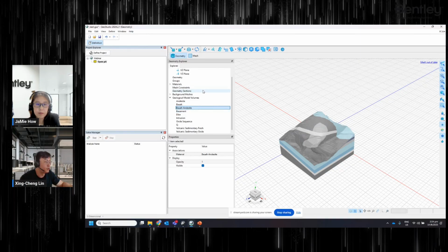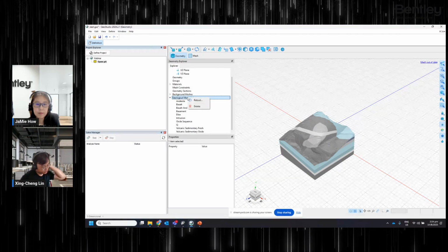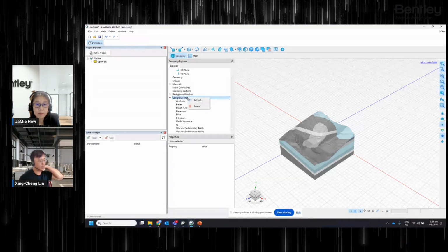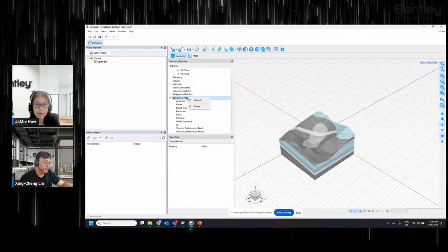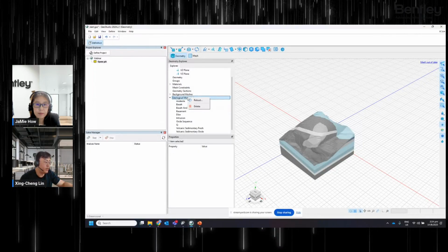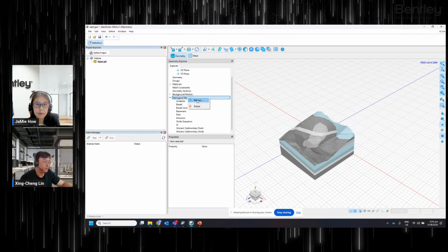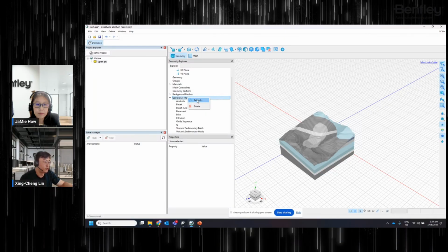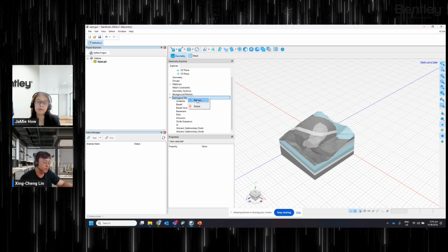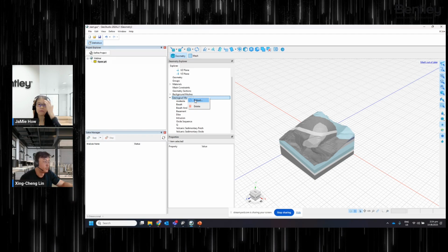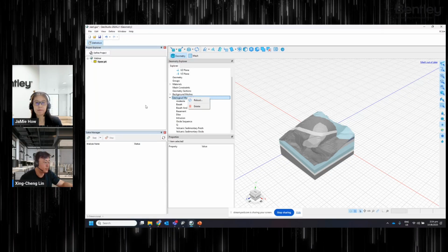All right, so this model is actually dynamically connected. So let's say for the case when the geologist was to go and update the model in Leapfrog Works and publish it to the central server, all I need is to right click on this button to reload the model inside GeoStudio to pick up whichever new settings or changes have been done by the geologists. So the model will be updated automatically.